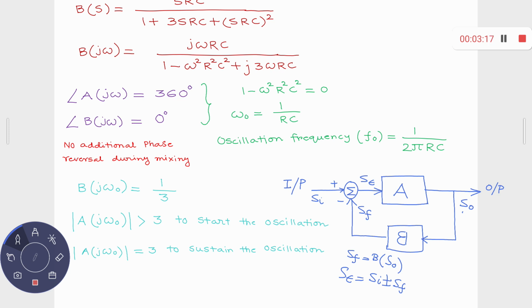You have seen that if the actual input is like this, the input getting from the back network would be something like that, reduced, but the phase is opposite. Whenever it goes positive, this goes negative, and ultimately the system becomes stable. That is the notion of negative feedback.